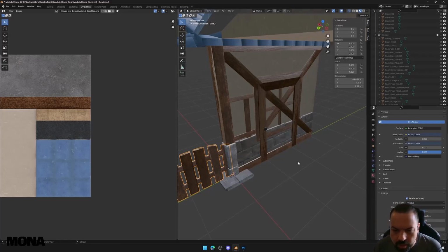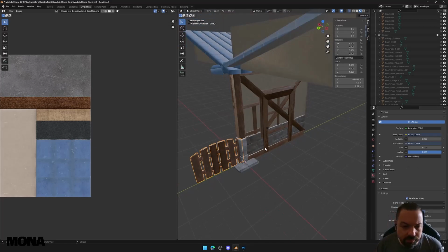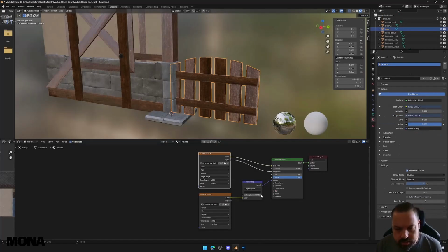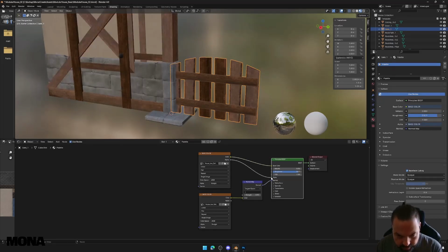So yeah. Now, with alpha, that's a little bit different. So we can look at, say, we get rid of roughness and we want to put it into alpha. So that's down here, right? Now, nothing's going to change because this is not an alpha material yet, right? So two things with alpha. One, you have to enable backface culling. If you turn it off,